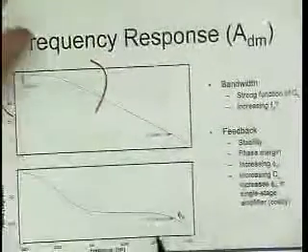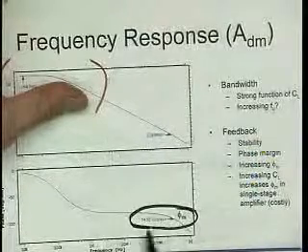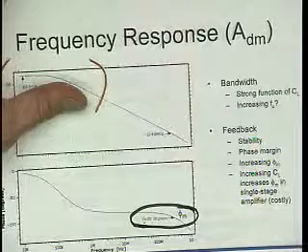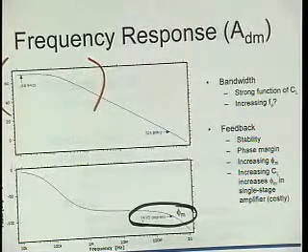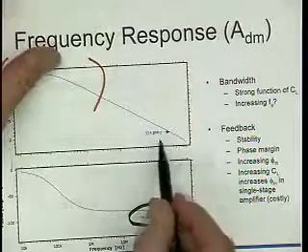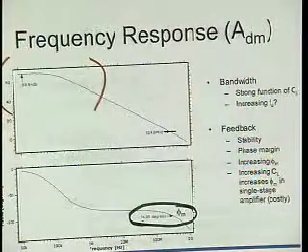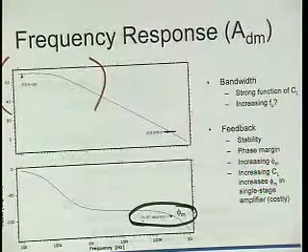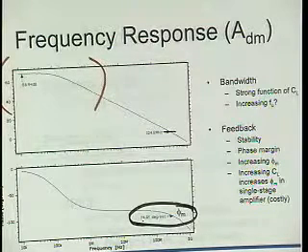So this analysis here, specifying a unity gain phase margin of 75 some degrees, is for a very, very special case, namely that the feedback factor was unity, right? So implicitly, because I picked this up at unity gain, I implicitly assumed that somehow I put the unity gain feedback around this amplifier. That is very practical.